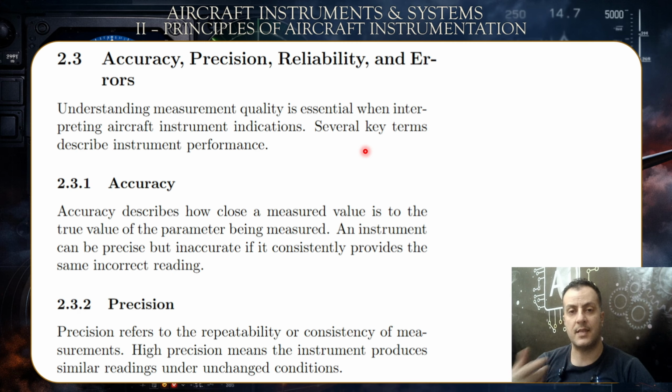In the same way, you would have a difference between the magnetic north and the perfect north when we're talking about the heading of the airplane. The direction of the magnetic north is different than the perfect north, so you would have the excursion when it comes to the directional gyro, the heading of the aircraft.